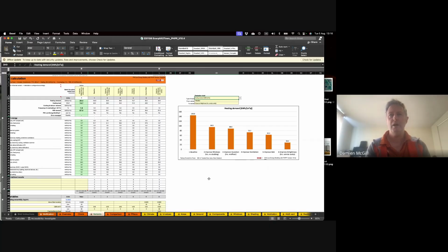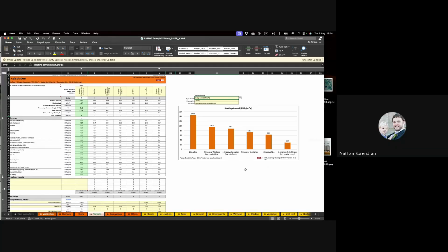And then, on a retrofit house, ceiling insulation all day. Ventilation doesn't have such a payback unless you're getting super airtight. But fresh air is important. Nothing else matters if you can't breathe. Yeah, I could make some comments about the prices that people charge for MVHR systems when it's basically just a box with two fans and a plate heat exchanger in, but that's maybe a conversation for another day.